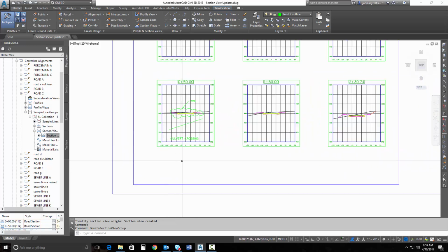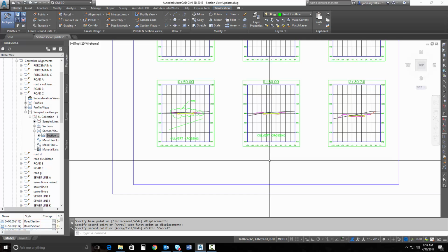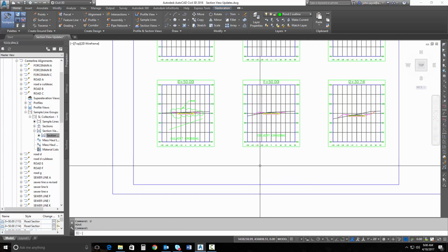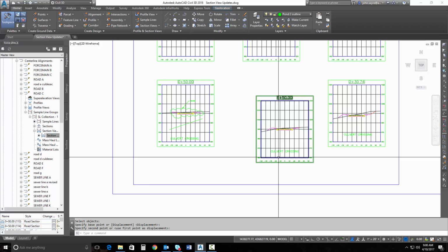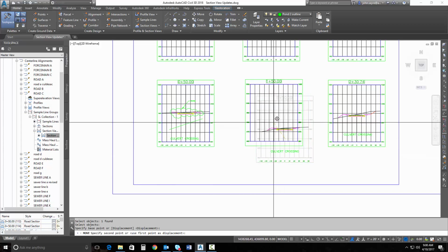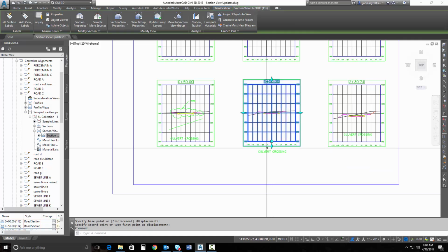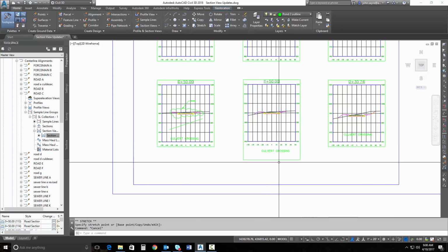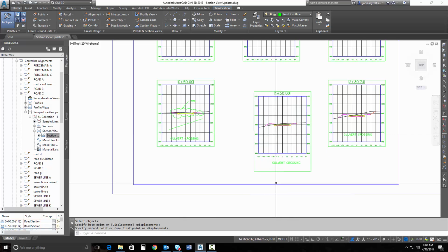Also, if we have text that is below, or maybe we add to each individual cross section, you can see here I could copy this text to multiple cross section views, and I can move this section and the text moves with it. Now, if my text is below, I can grab my frame and move that down, and then when I move my cross section view, everything updates.